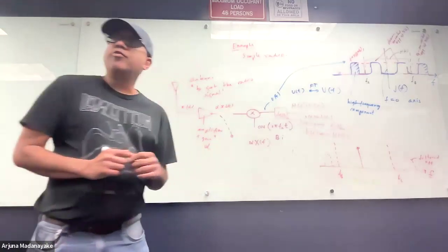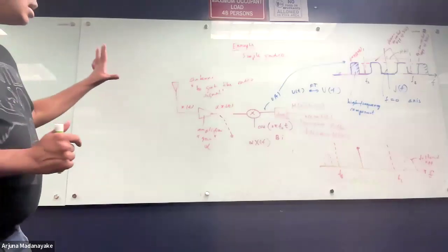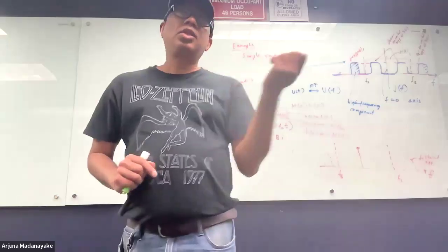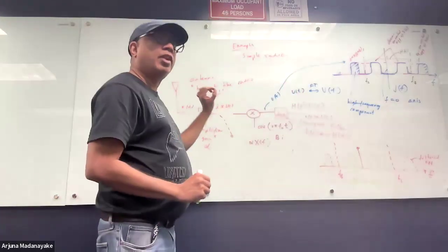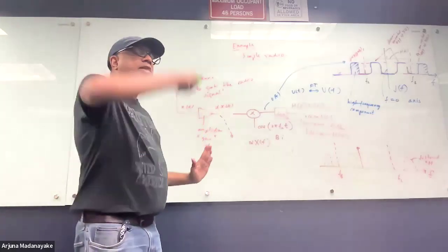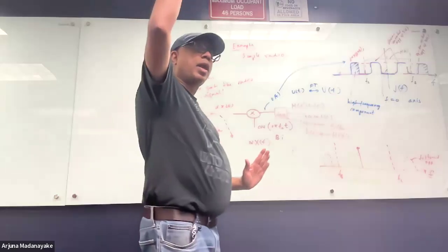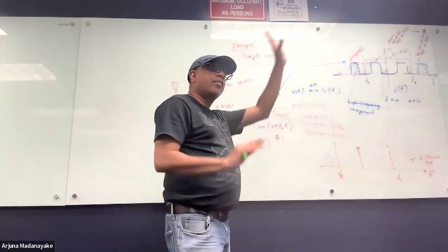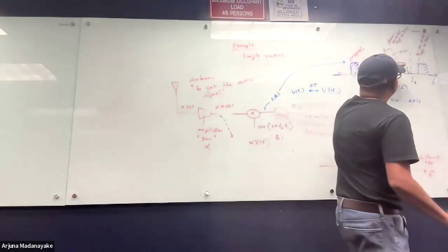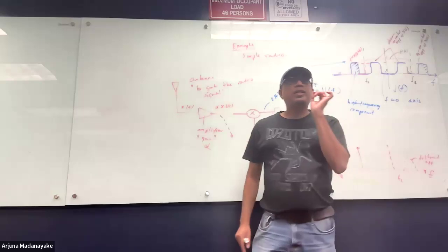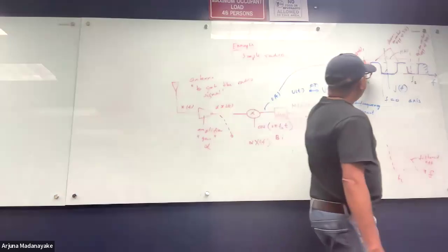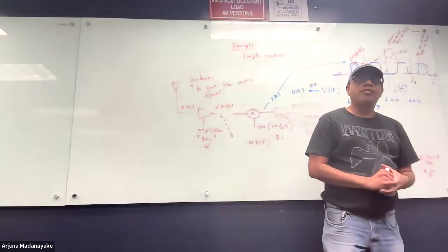It might sound a little confusing because today is the first day you are seeing this, but the point here is that you now have the mathematical tools to describe very precisely what happens when radio signals are propagated. You can turn the frequency, scale it up by multiplying, bring it down. You can filter and get rid of parts of the spectrum, and you can define what shape this filter has by carefully designing a filter which has the right small h of t, because this shape is simply a function of small h of t.